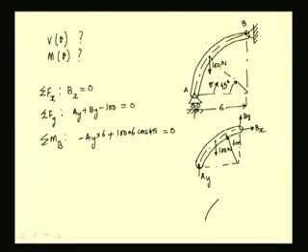Let me call this C and O. So, we are considering a section of this beam before the mid section C. So, at A we have the external reaction, and we have the shear force V transferred to the member, the axial force say H, and the moment M.